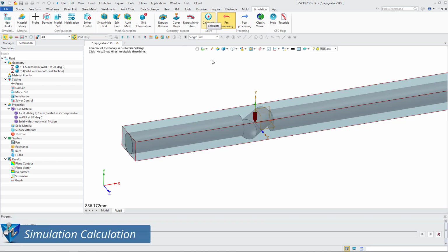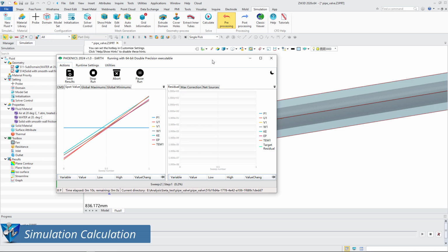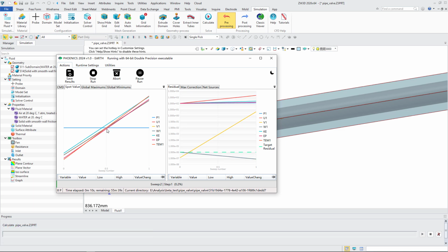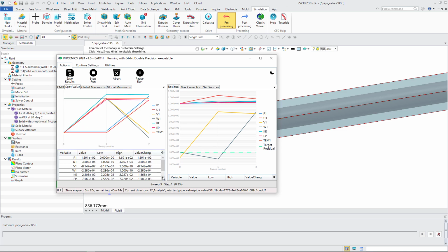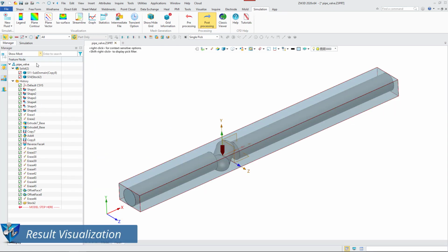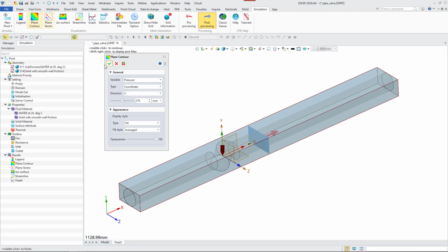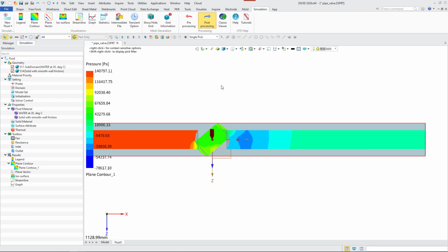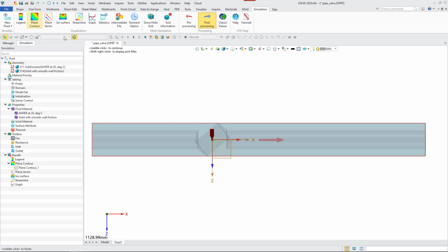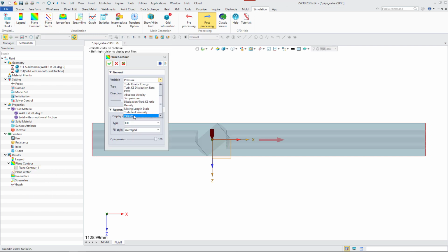After submitting the calculation, monitor data in real time via the monitoring panel to assess result stability. The fluid domain of the valve is transparently displayed, and the pressure contour of the cross-section of the valve is created. The results show a significant pressure difference between the front and rear of the valve, with negative pressure observed downstream. Generate a mid-plane velocity contour.